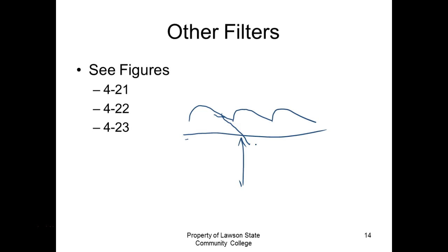The ripple voltage is decided by what? Two things. What determines the ripple voltage? Well, three things. The size of the what? Capacitor. The load current. And of course the frequency, but usually the frequency on our power supplies over here is set. The frequency of the input. So those three things determine how far this valley goes down.